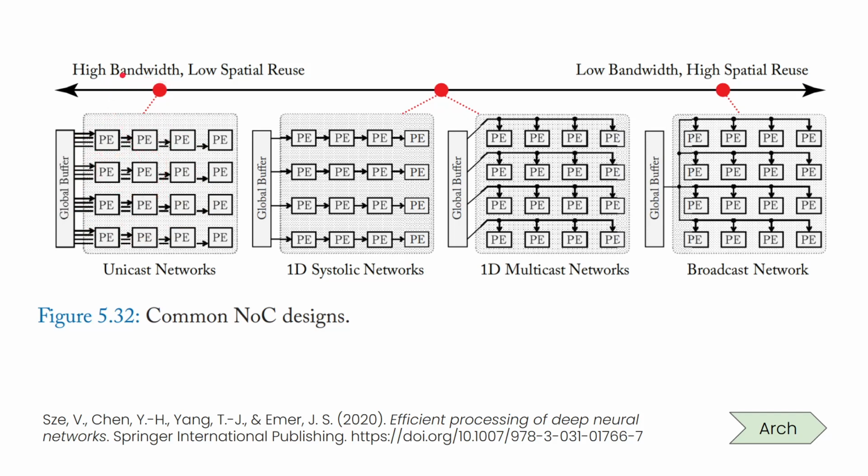So there's a lot of bandwidth, in that the maximum possible amount of data that can move in a cycle is like 24. It's a lot. And as we move forward, you'll see there are fewer wires. Here we have 16. Here you have 4. Here you have just one long wire with many different heads. So out of all the network on chip designs, this unicast network has the most bandwidth.